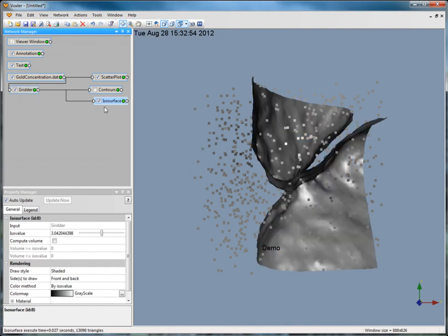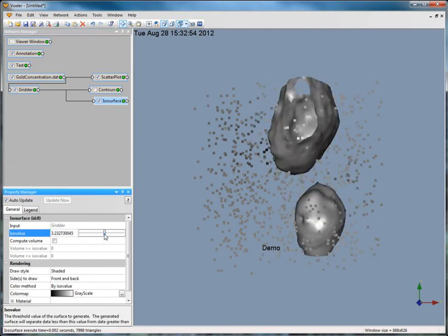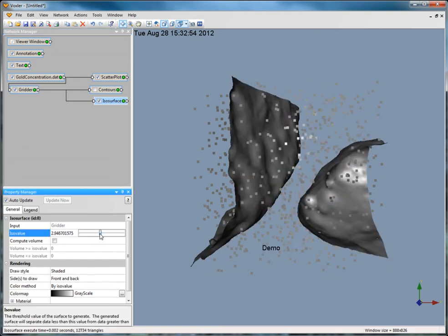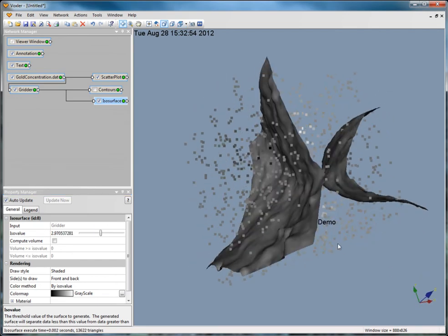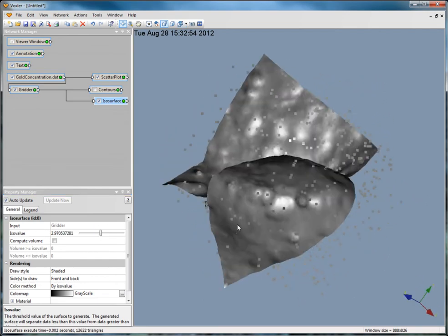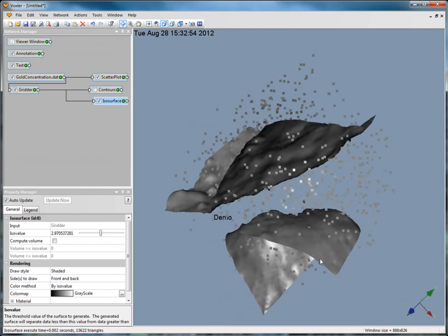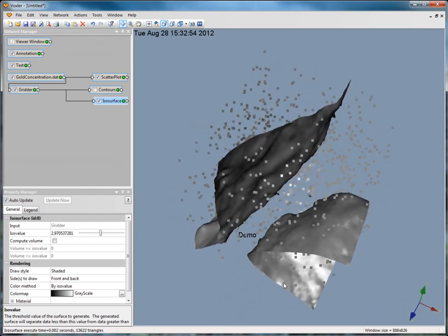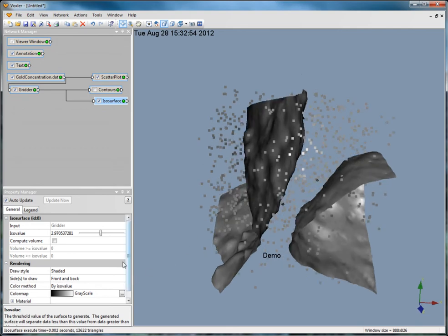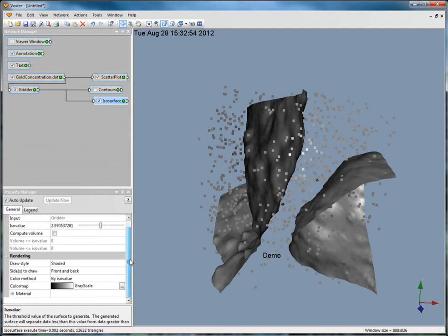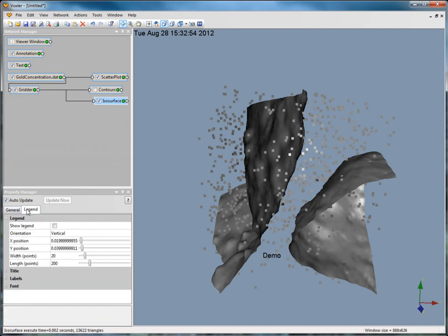An isosurface is a surface of constant component value, displayed in 3D. The isosurface separates regions less than the selected value from regions greater than the selected value. All points on the isosurface have the same value. You can change the ISO value, drawing style, color method, colors, transparency, and the shininess of the isosurface. You can also choose whether a legend is displayed.